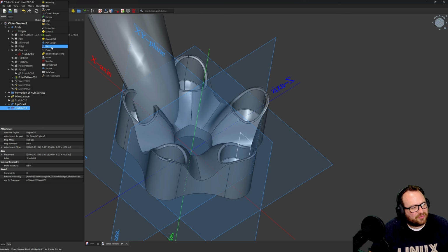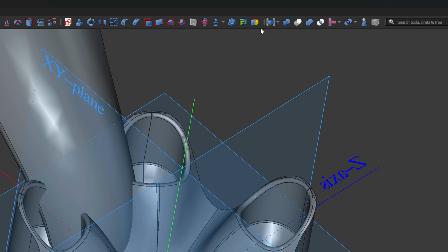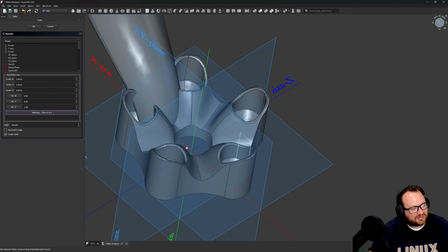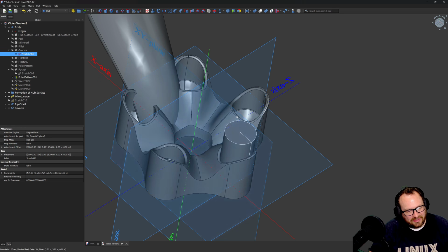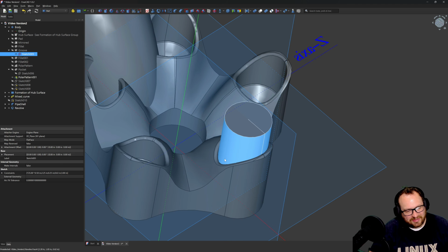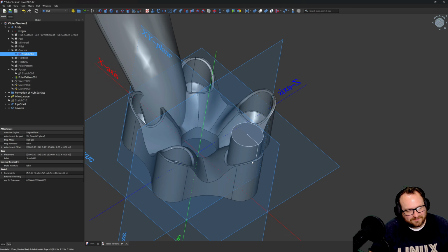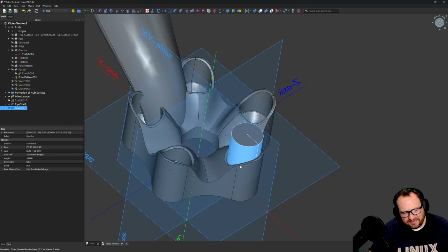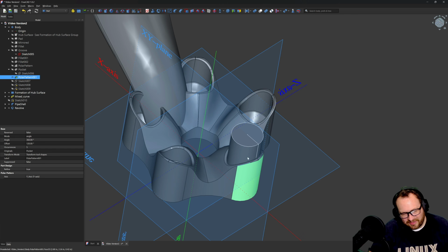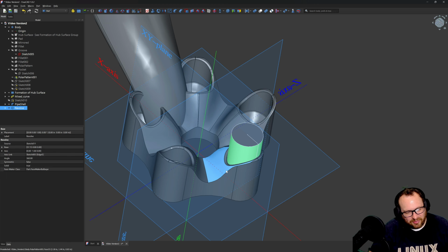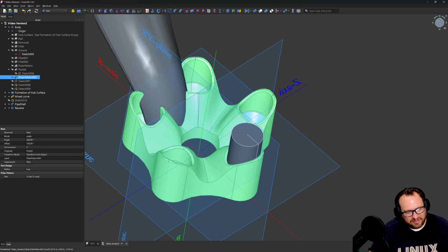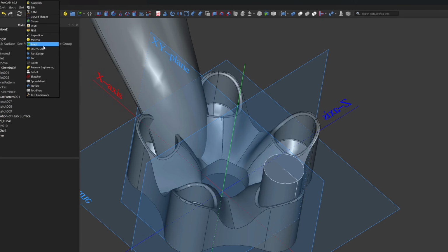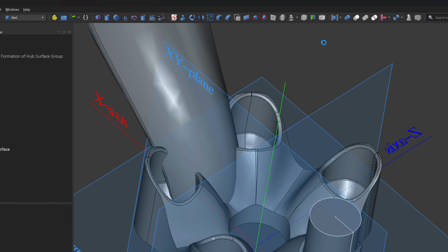We're going to go to our part workbench now. And we're going to do a revolve, right? There's our revolve. We'll choose an axis by selecting a reference there, and we'll say OK. Just like that, we've generated something that sits right inside of that hole. And again, these are not merged bodies, so we don't really have to worry about this coming to a point where there's a fillet on the inside right there or anything like that. We'll head over to draft because we need to pattern this for a proper trim.